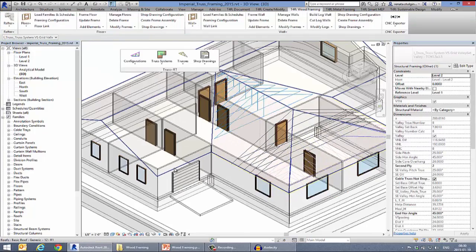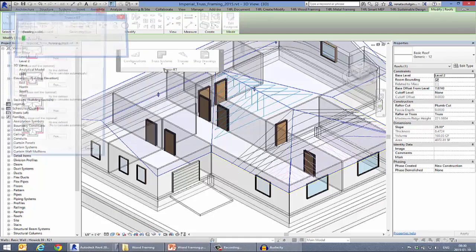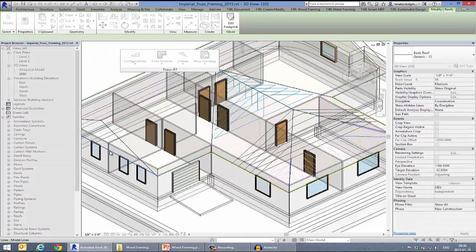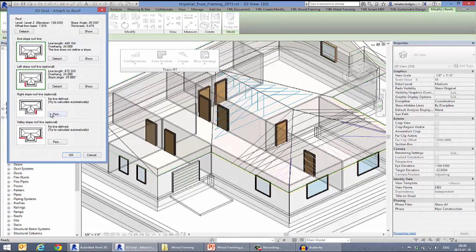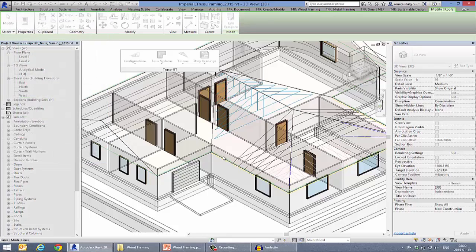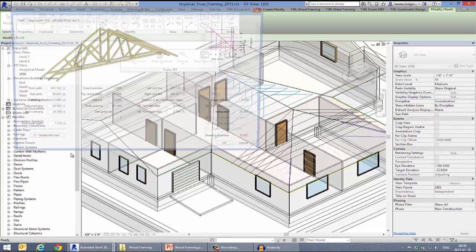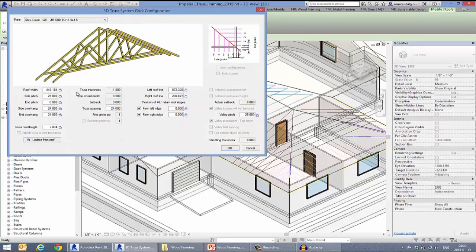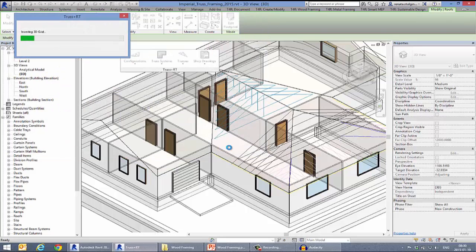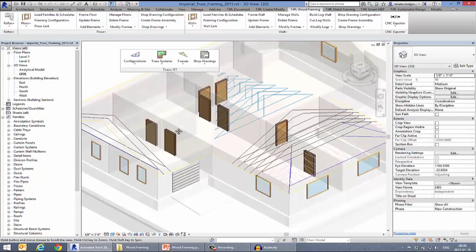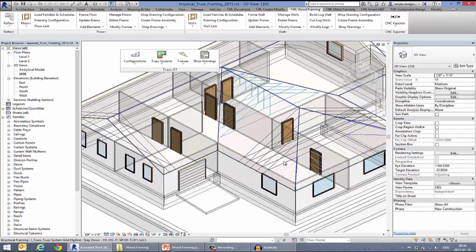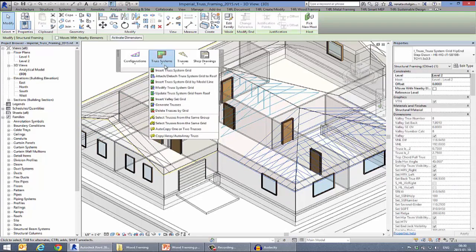Okay, and the same we can do just very quickly for another side of the roof. And you can see that here it's very easy to predefine the sides of the roof. The tool will read all information about the pitches and about the slopes. And after that, we can generate trusses.